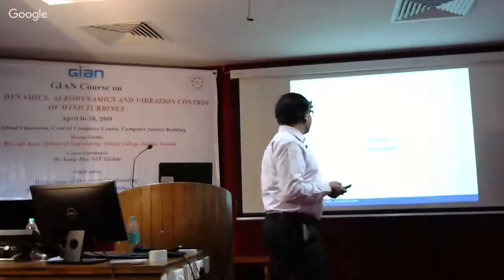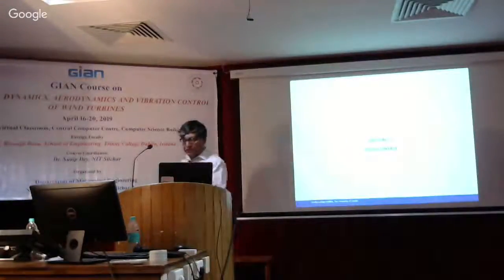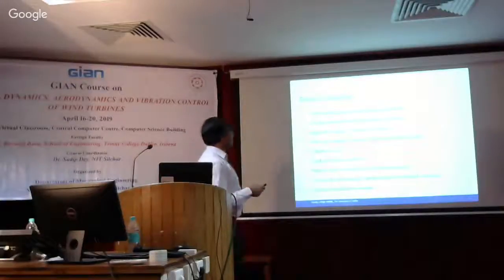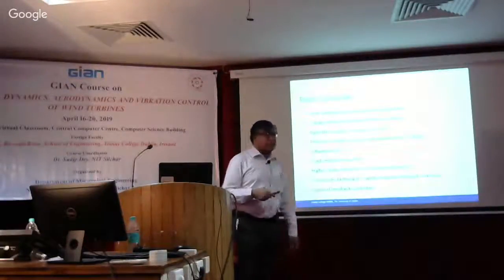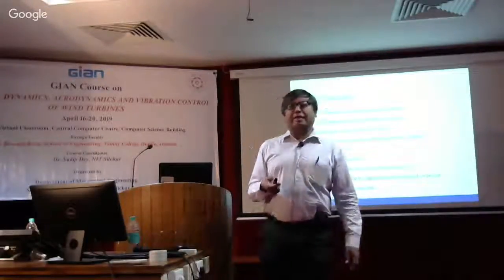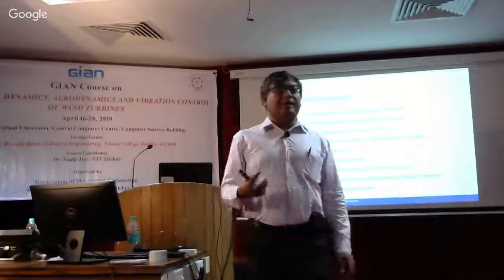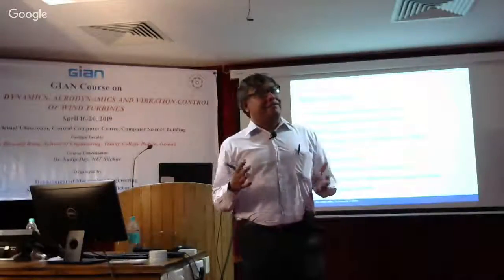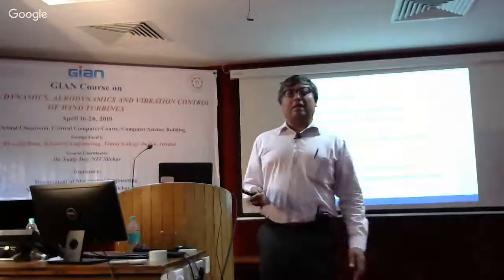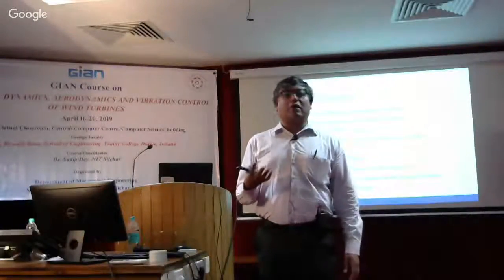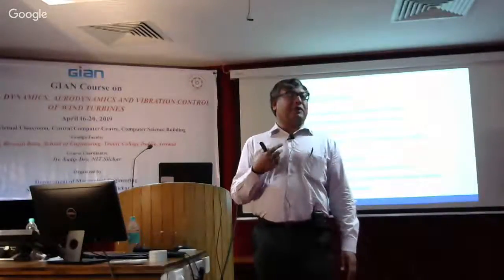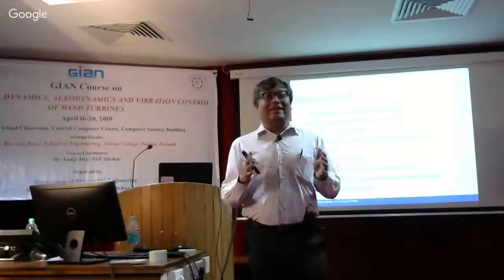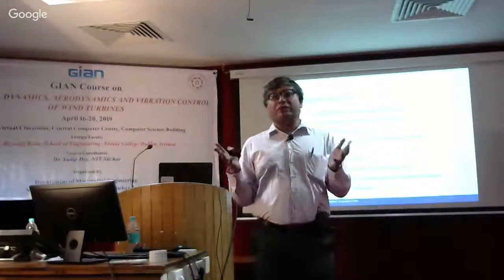So going back to, yeah, today's first part is on pitch controller. Primarily, the power, as you know, that is generated in a wind turbine has to be saturated to the rated power. That is really to safeguard the generator. The wind speed could be significantly high, which actually won't be really useful for us because we won't be able to capture the power. In fact, we are only able to capture the power within a typical range of 5 to 15 meters per second. So anything less or more than that wind speed range is not much of use to us.